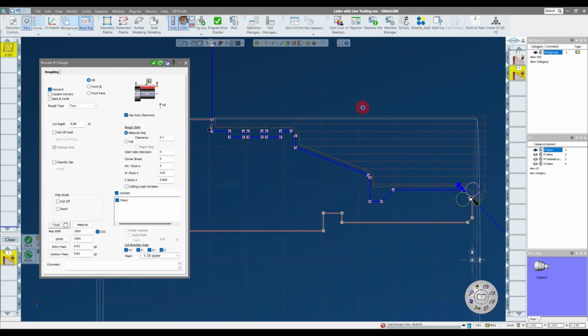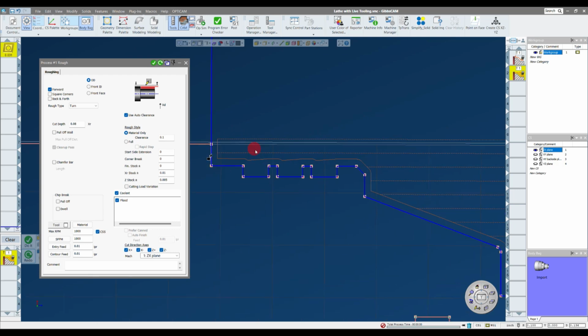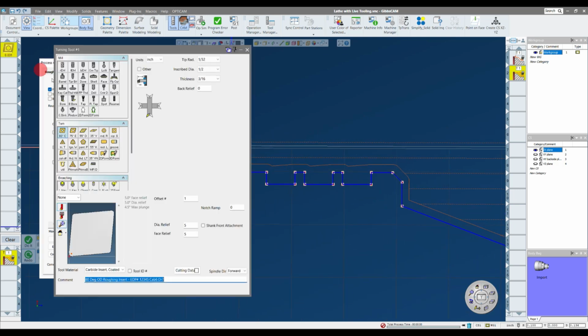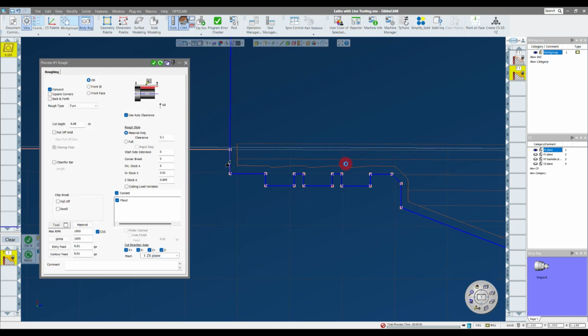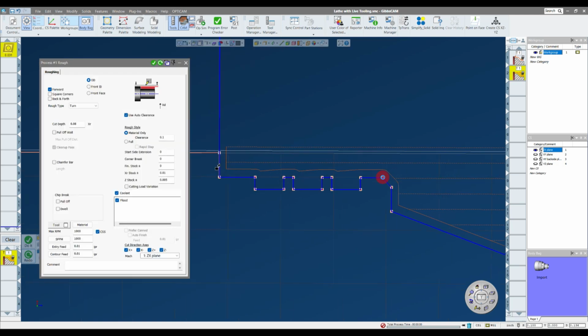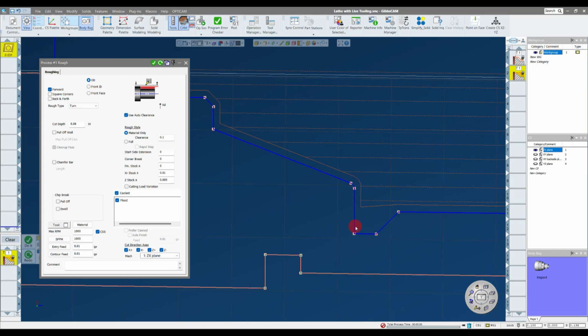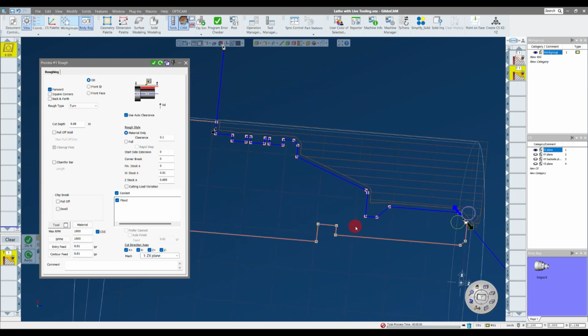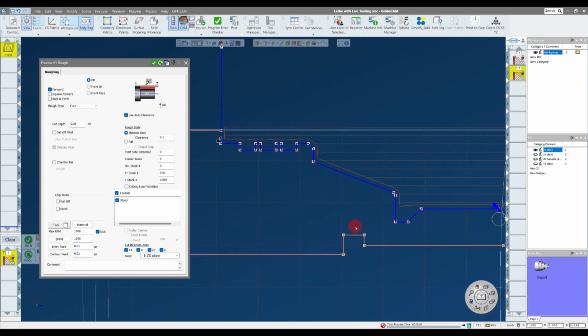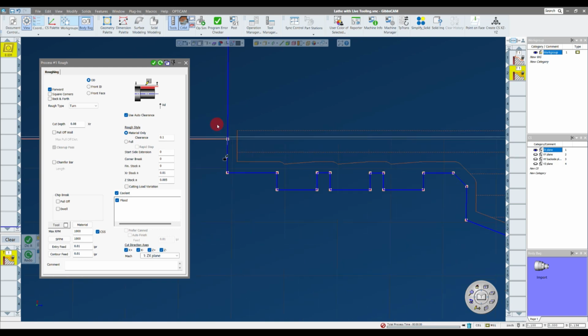All right. So one of the things you'll also notice is that because my tool geometry has a 5-degree back turn angle, it's trying to drop that tool into these OD grooves and also my relief down here on the front of the part, which is not a huge deal depending on the material, but it also may rub the insert and generate some heat and reduce tool life, things like that. It's probably not something that you would really want to do.